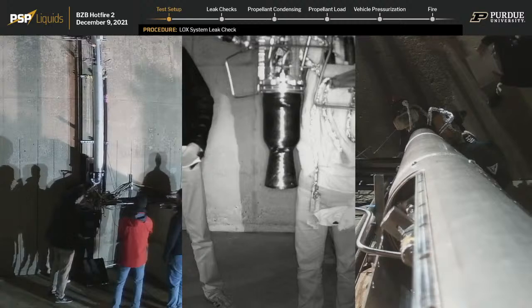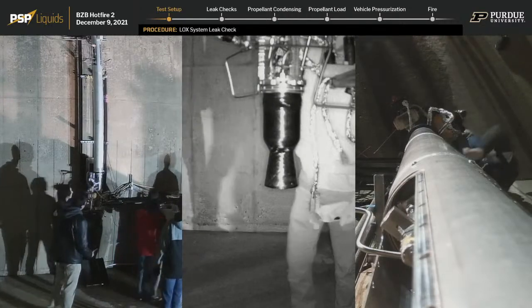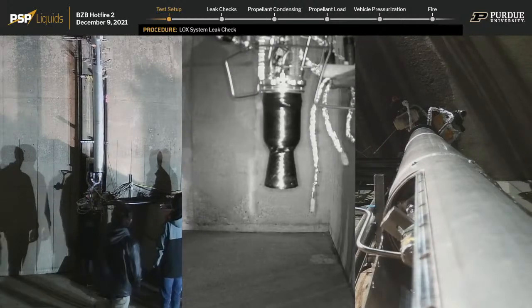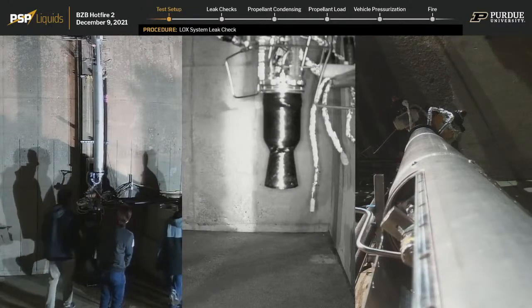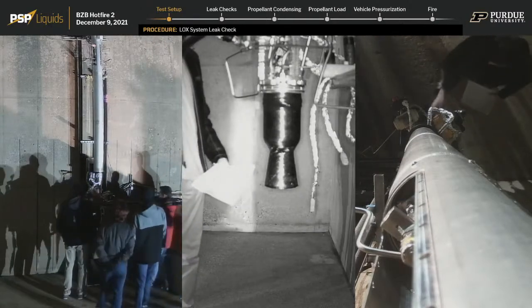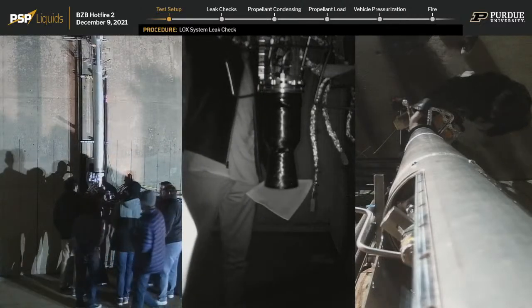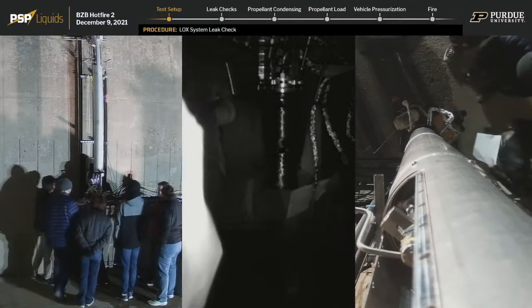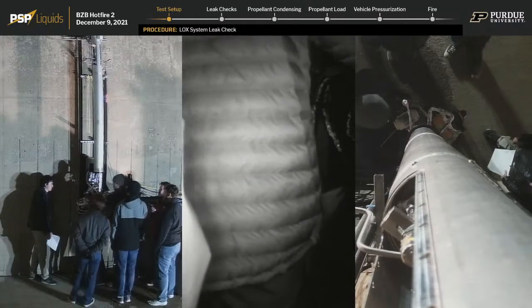Is there any particular reason why tightening under pressure is so hard? So the force balance when you're tightening under pressure involves gas also pushing against the force of you trying to tighten a fitting connection. And in addition to making it harder, there's also the possibility of a fitting connection becoming undone under pressure, which is a dangerous situation. Go ahead and tighten the fittings. Over.